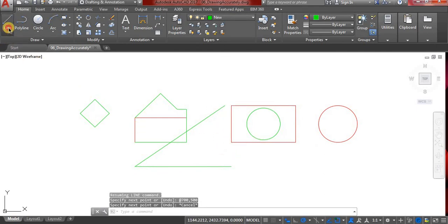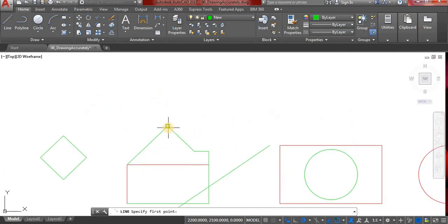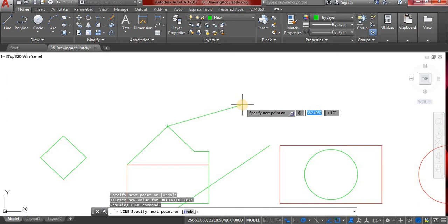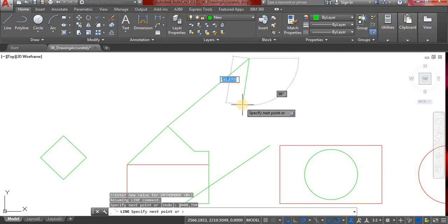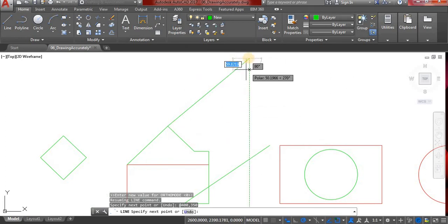Let's go ahead and do it again. I'm gonna pick this point. Wait, let's just do this point. I'll go to that direction, but I'll hold shift and number 2 for @ sign. You see, @ 300 something and less than 17. I'm gonna get rid of that. How? I'm gonna pick a number, okay, 400, and then a comma. That's how I cancel it. Now I'm inputting the x and y values. So that's the trick, and it's really useful. Enter, and there it is. Relative to this point, it gave me that new endpoint.